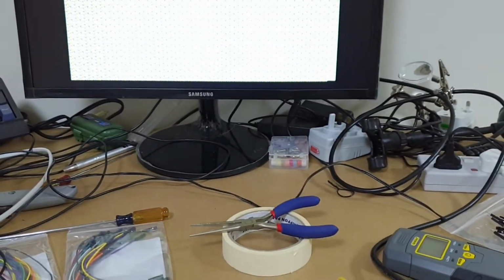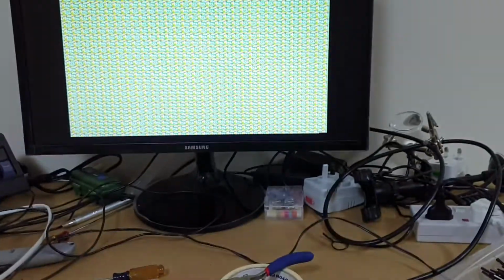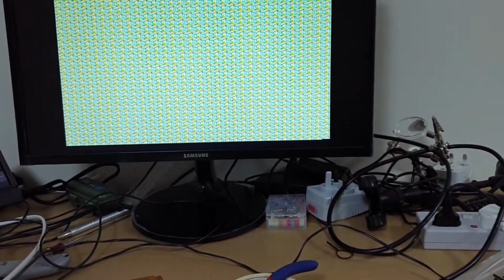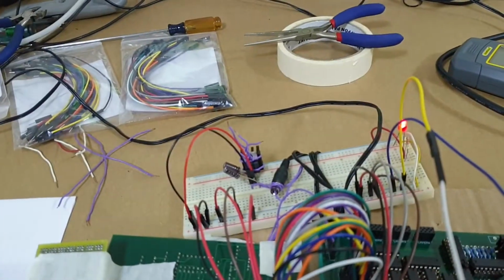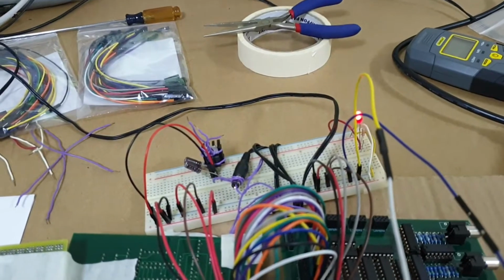When the voltage cutting off like that is very indicative, and the RAM pattern changing is very indicative of the voltage just dropping far too low, because the voltage regulator is getting far too hot. I really do need to invest in a better voltage regulator.